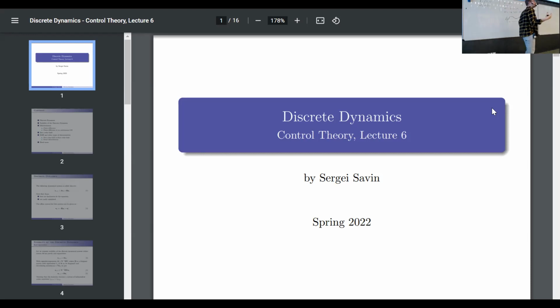Discretization is when you say that you can evaluate something at the moment of time 0, at the moment of time t, at the moment of time 2t, but not between those. So quantization is in value, discretization is in time. That is quite confusing, because the word discrete kind of implies this step upwards too. You can say it is a discrete step, right? But discretization is specifically talking about time.